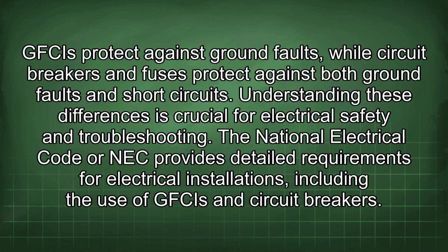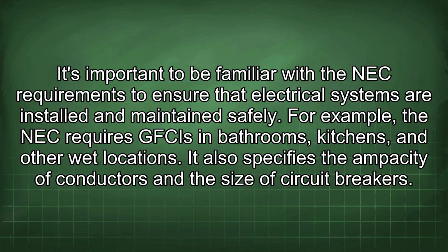The National Electrical Code, or NEC, provides detailed requirements for electrical installations, including the use of GFCIs and circuit breakers. It's important to be familiar with the NEC requirements to ensure that electrical systems are installed and maintained safely. For example, the NEC requires GFCIs in bathrooms, kitchens, and other wet locations. It also specifies the ampacity of conductors and the size of circuit breakers.